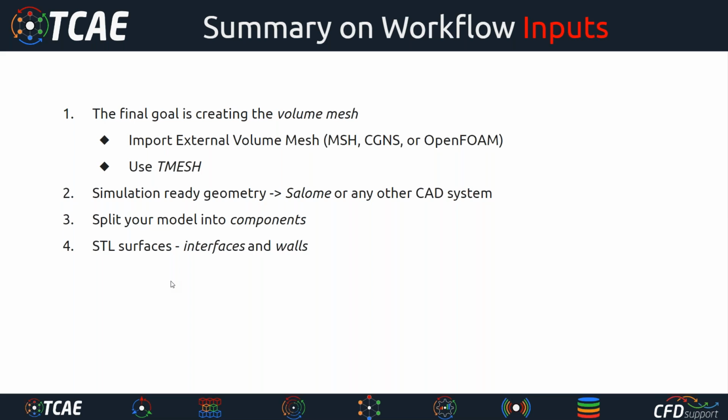And interfaces, they don't really exist. They only act like imaginary surfaces, because we want to be able to prescribe the boundary conditions and know the flows through them, etc. Yes, so this is the way how you do that. This is what you want to achieve, to be able to create your volume mesh with T-Mesh.